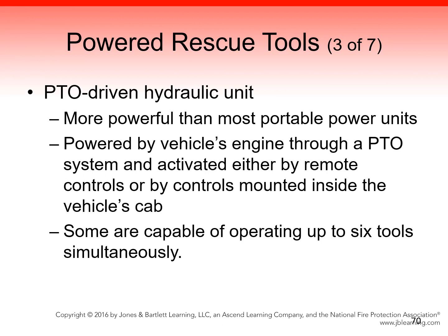Then the system pressure builds, and the second mode, a high-pressure, low-volume mode, 10,000 psi, is activated to deliver added power. Sometimes this switching of modes can cause a few seconds delay in the unit's operation. During this gap, the operator must hold the load position until the second mode kicks in and the fluid pressure builds in the system.